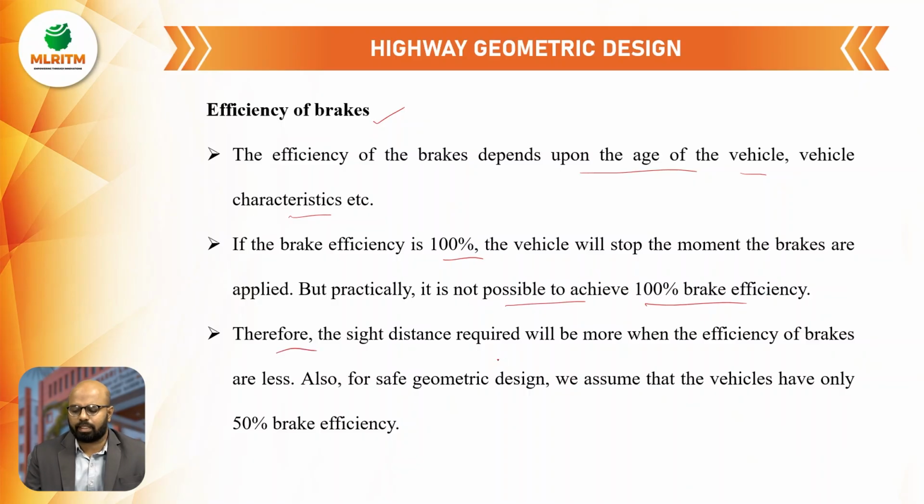Therefore, the sight distance required will be more when the efficiency of brakes is less. Also, when we are designing for safe geometric design, we assume that the vehicles have only 50% brake efficiency. That is the assumption we make while going for the safe geometric design.